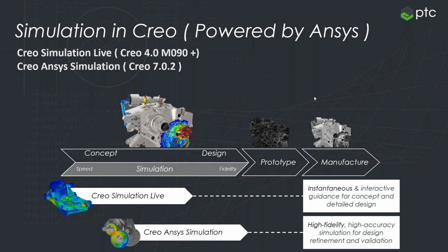With Creo ANSYS simulation, you can control the mesh, you can refine it, things like that, where you can do some linear contacts. You can apply joints. Some of you may have heard of the Ansys AIM product. It's pretty much that one that's embedded in here, fully working natively inside of Creo, right?